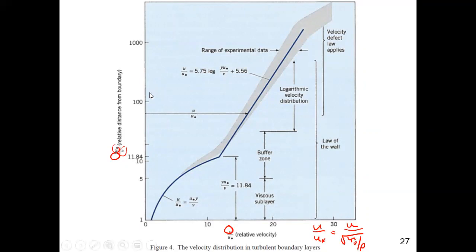And why I bring it to your attention: where you see the yellow highlight lower left, that's laminar. These are the Blasius equations, whether you know it or not. You will see these other highlighted areas called the logarithmic velocity distribution, and you can see the equation for the logarithmic velocity distribution up here. This is used a lot in streams.